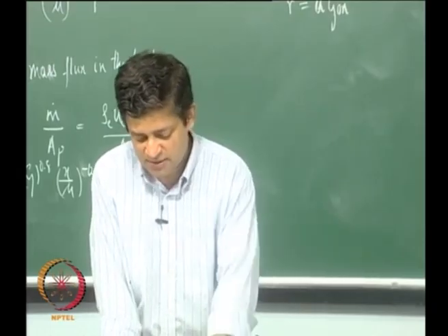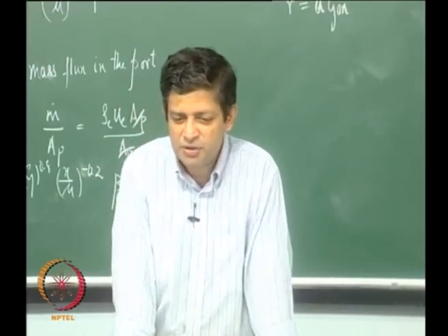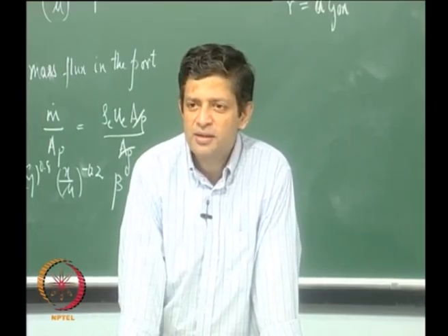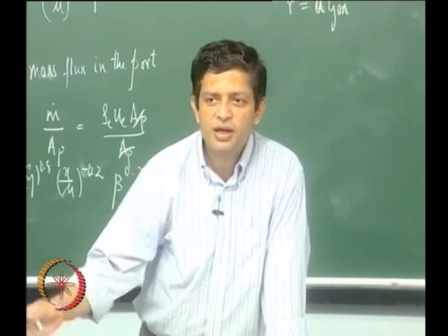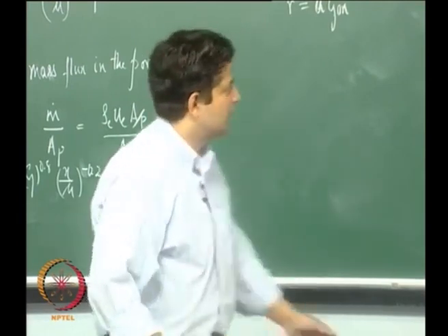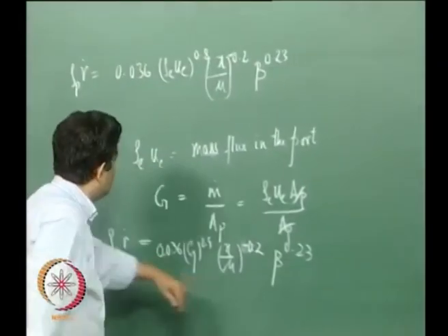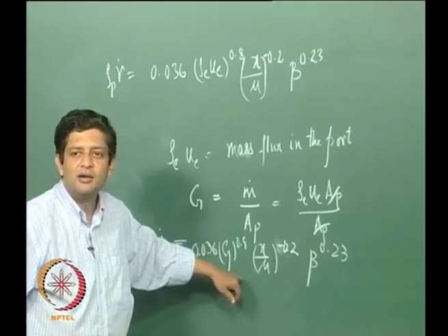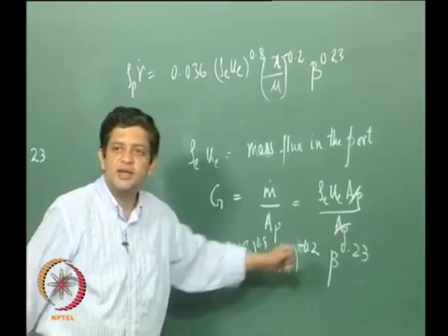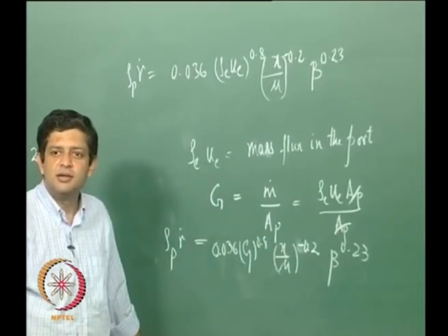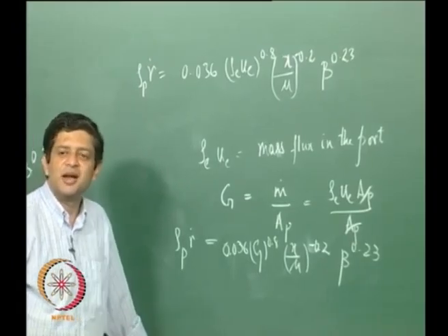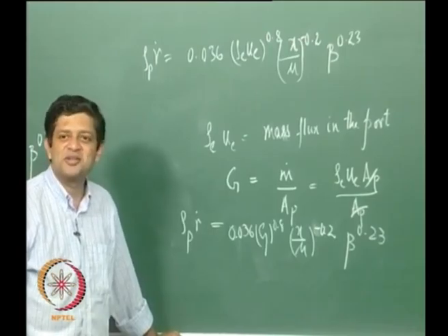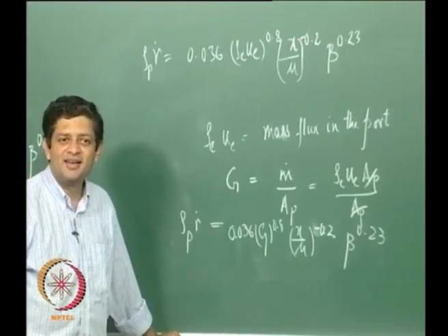Now let us look at the problem that we had discussed yesterday with regards to what happens to burn rate as we proceed from the head end to the nozzle end. If you look at this expression, it looks like the burn rate should decrease as you increase x, but I had said the opposite yesterday, right? Is that correct or is that wrong?